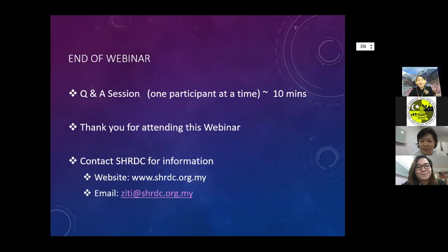Okay, that depends on your PCB. If you have a big PCB board with a lot of free space, it's always better to put larger trace width for your power and ground. So this is acceptable, provided that you have enough space on the board. But if you have a very small board, you don't have enough space, and you can't do that. So it depends on the situation. But it's acceptable. It's always good to have bigger traces, actually.